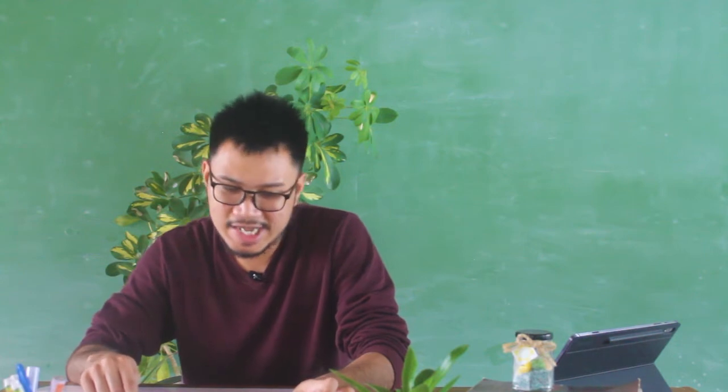Okay, so let's do this. We are still going to use the concept of the method of sections, wherein we have to cut a beam at a certain point, and we will generate equations there. Why equations? Because instead of having a specific distance, we will always use an arbitrary location, said to be a distance of x perhaps.